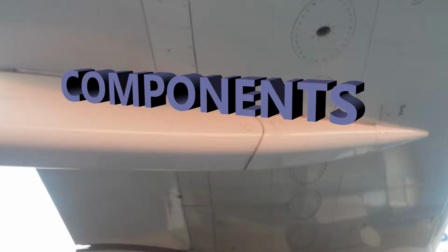Probes have mounting brackets, and they're usually mounted in the lower bracket and also at the sleeve at their upper end. Pay attention to the brackets if you happen to be working on this stuff. Remember, I just said heightened awareness. If you see any cracks, this is what happened with an APU that had a couple of broken mounts, and it dislodged the APU while the plane was in flight.